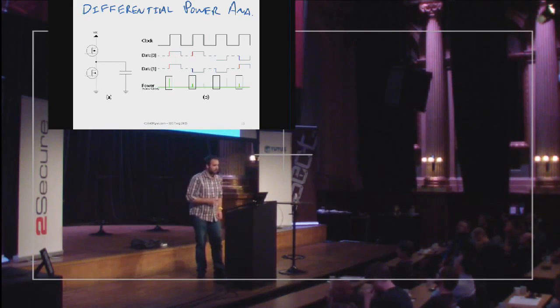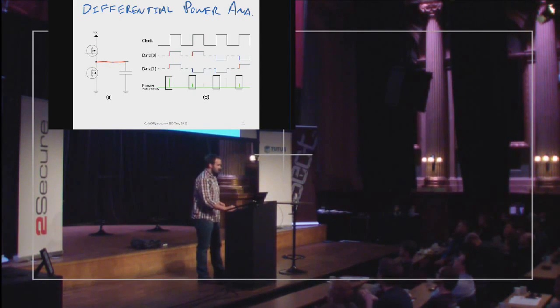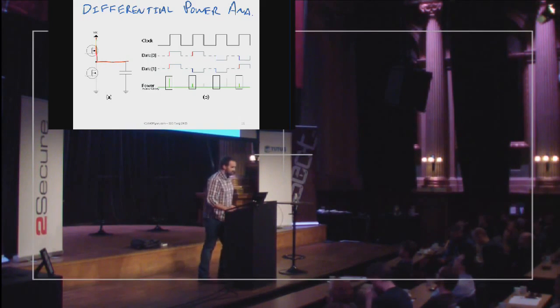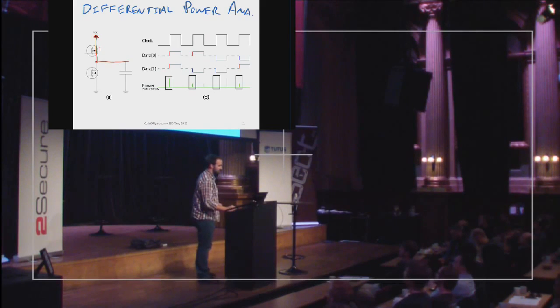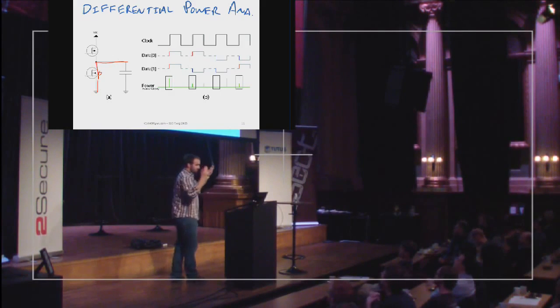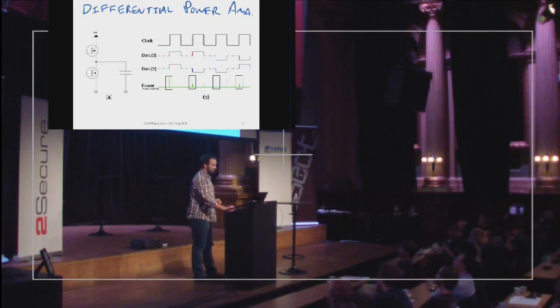How this works is that on a digital device, internally, it has these lines that it's switching. There are bus lines that run all over the chip, and the microcontroller can switch these lines either high or low. If it changes it to a 1, it connects the VCC, the positive supply, to that rail. If it changes it to a 0, it connects the ground, or the 0-volt supply, to that rail. Now that rail is literally a piece of wire inside the chip. It has some capacitance. So really what we're doing is changing the voltage on this capacitor here.